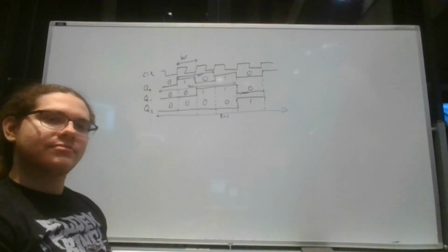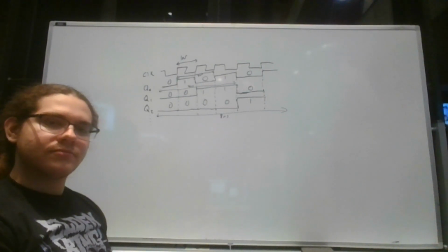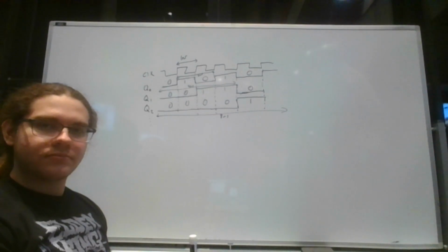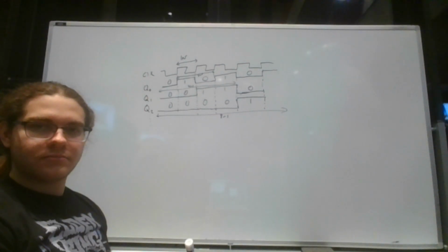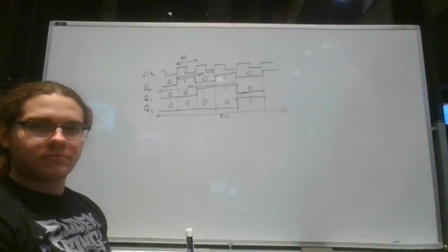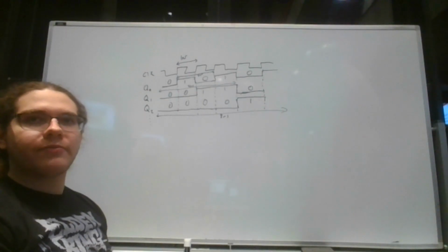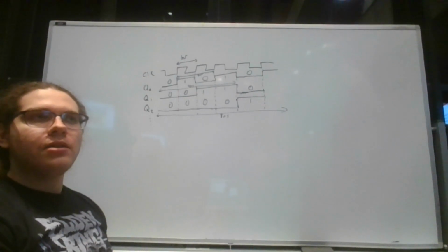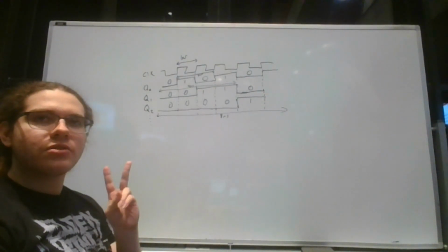I do have a question on the term registers though. When we're talking about registers in SystemVerilog, we were thinking more of flip-flops, right? But now when we're talking about registers in RISC-V assembly, are those still the same registers? Registers are flip-flops. They are the same. There are two main distinctions.